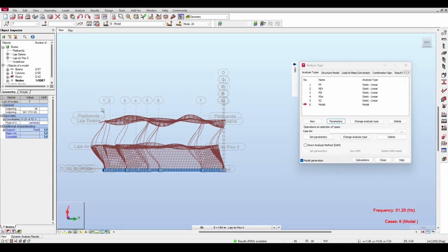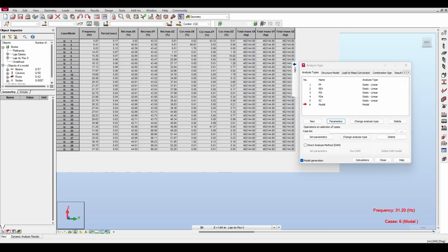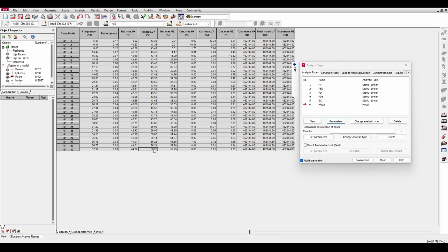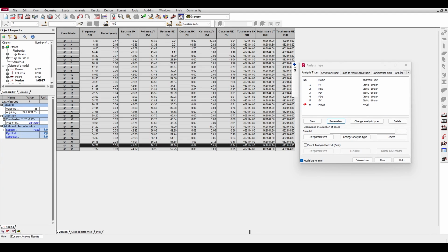I know that the slab seems to be stationary, but the shear walls have a net movement in Y, and that's why suddenly you have a spike in the Y direction with yet another 40%. So you can see how increasing the modes actually improves the outcomes of the analysis. Keep playing the trial-and-error game until we reach a certain mass participation. Let me say that I am targeting 85% mass participation. Allow me to show you.